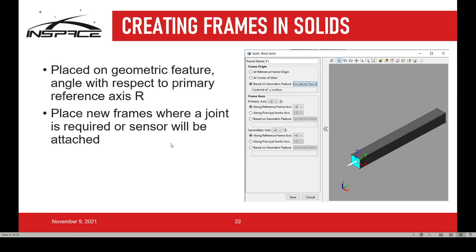You also want to be careful with the orientation of this axis, because there are some joints that are only going to work along certain axes, which I'll get to in a second. You don't want to mix up your X, Y, Z axes because you need to constantly reference them to make sure your link is not moving sideways as opposed to up and down.